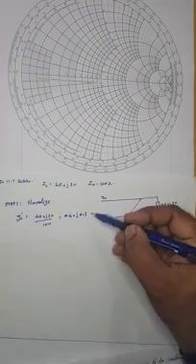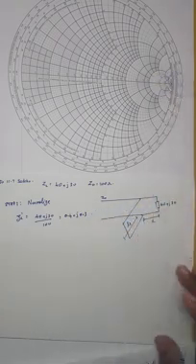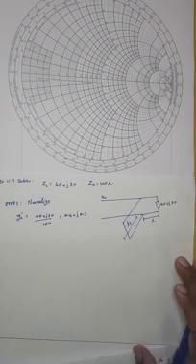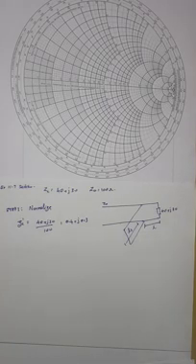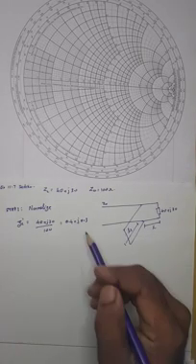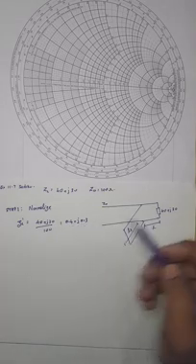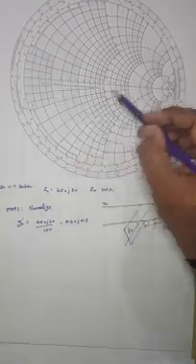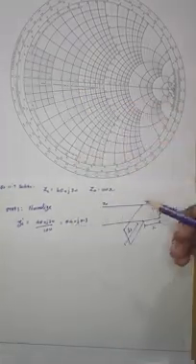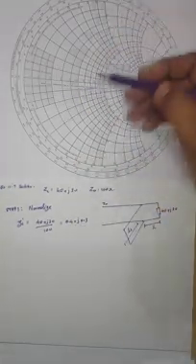Now this normalized load impedance is what we feed as input to our Smith chart. So let us go ahead and try to feed 0.4 plus j0.3 into the Smith chart. Since we have a plus, we understand that we've got to be concerned about the upper half.